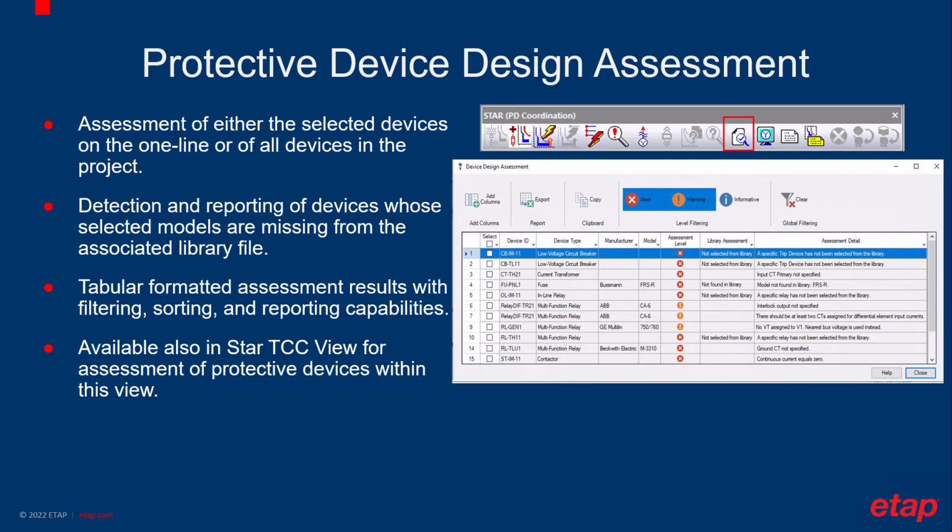When we are doing protection and coordination studies, having all protective device data entered is the first requirement. Without this information, we cannot plot time current curves. The application of this tool is to troubleshoot and verify the entered data for all protective devices, so that we can identify all the missing information and the issues we have in the current project.